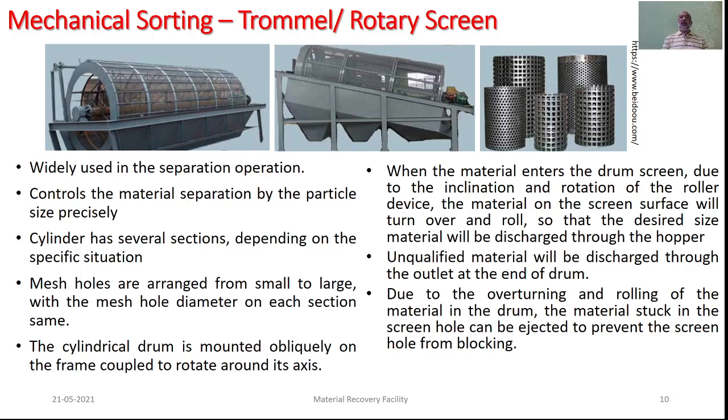It can also be employed at secondary storages, at the transfer station, at recovery facilities, and even within recovery facilities at various levels: at the point of initiation, intermediately, as well as at the end. Even at an ultimate disposal facility like a landfill, the trommel or rotary screens can be used beneficially.